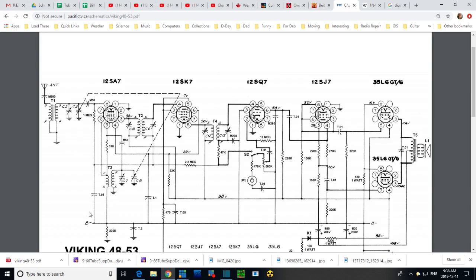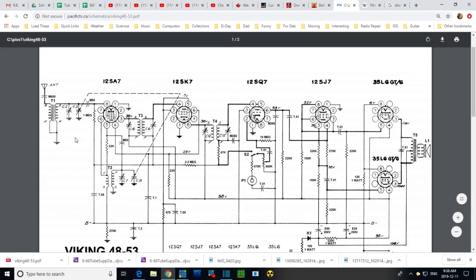And what that allows in this receiver is to boost up the radio's sensitivity to something enormous. Without taking care of the image problem, having an extremely sensitive radio means you're going to hear a lot of images. And you won't really realize that that's happening. You pick something up, something comes out of your speaker. It sounds great. It's not where you think it is, though. So commercial receivers, military receivers, very high quality receivers have more and more pre-filtering out the front end here. All of it with the difficulty of tracking in the radio.